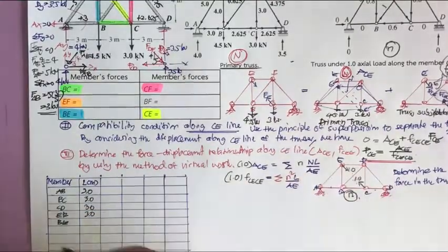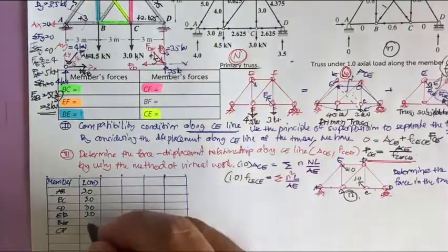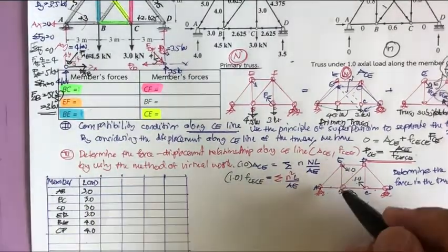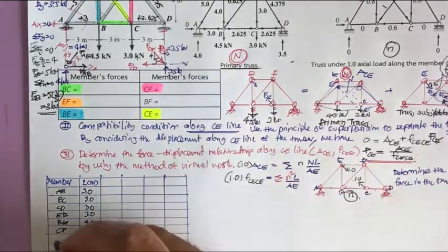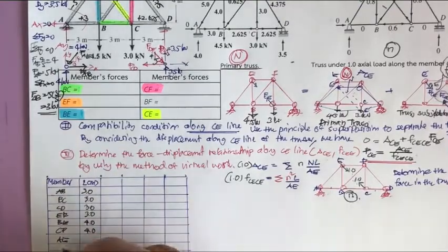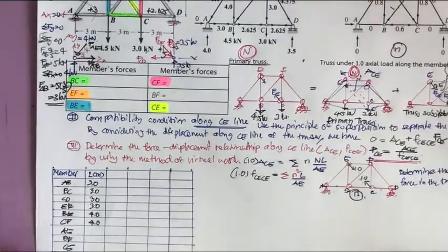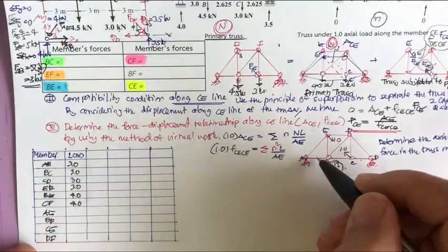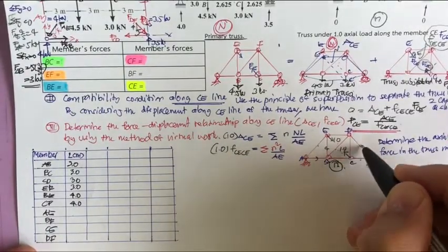Okay, next you may set BE and CF, and the length is going to be 4.0 and 4.0. And the last four, AE, BF, CE, and DF. If you do it like this, you get a 3-4-5 triangle, so this is 5, 5, 5, and 5.